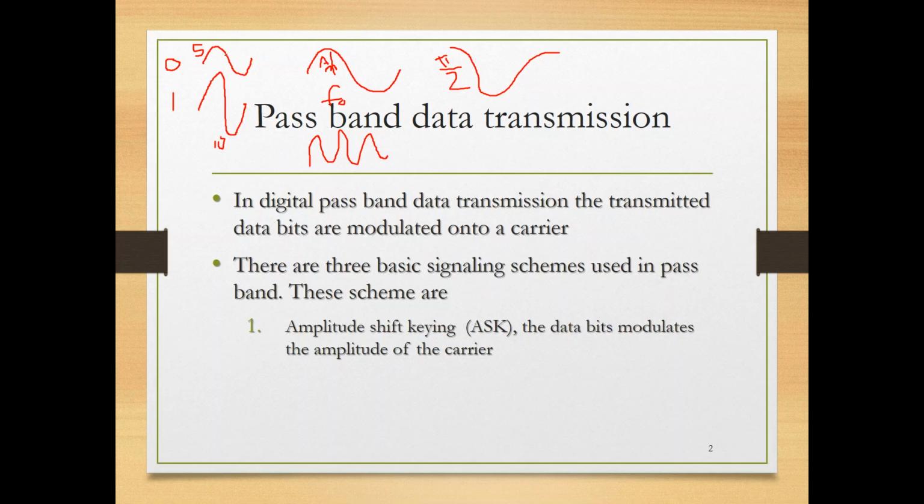So you send this through the wireless channel and it reaches the receiver. Before he starts communicating, the transmitter talks to the receiver and tells him, look, I'm using this mapping rule: whenever I see 0, I convert it to a sinusoidal signal of amplitude equal to 5, and whenever I see 1, I convert it to a sinusoidal signal of amplitude equal to 10. So the receiver understands the transmitter and saves this mapping rule in his memory.